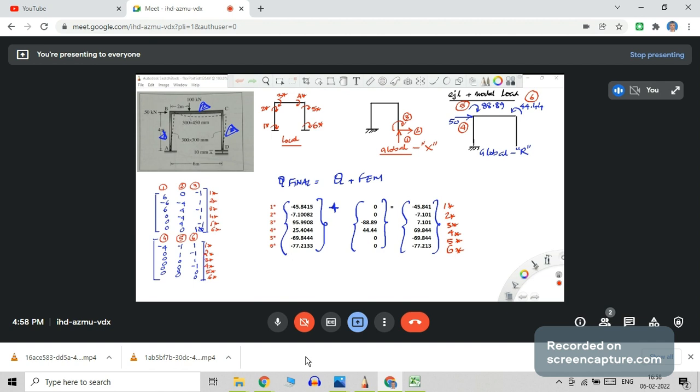So you can extend the same formulation to a beam, a continuous beam. It's only a matter of extending. It's not a new problem. Apply the same principle. Suppose you have a continuous beam, two or three redundant supports, and if one of the supports is settling, include that into the x coordinate, that support reaction, or remove that support where the settlement occurs. Remove that, then automatically one redundant will pop up, x1, x2, x3, etc. So same principle, nothing new. Try to extend this to that also.